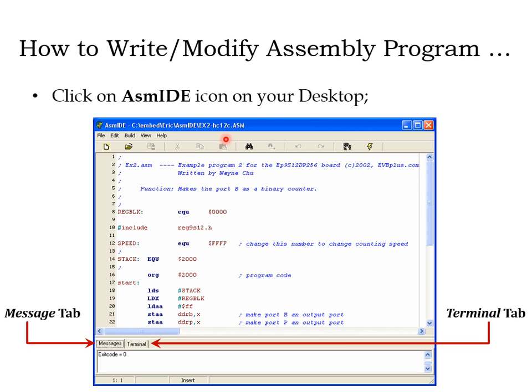In our program, all the extensions will be ASM because that's an assembly program. So it will automatically be ASM if you save it in the window here. Once you type it, you save it, and I will show you how you do all those steps one after another. But once you run the program, you will see all the errors and the list of problems, if you have any. Everything will come in the Messages window.